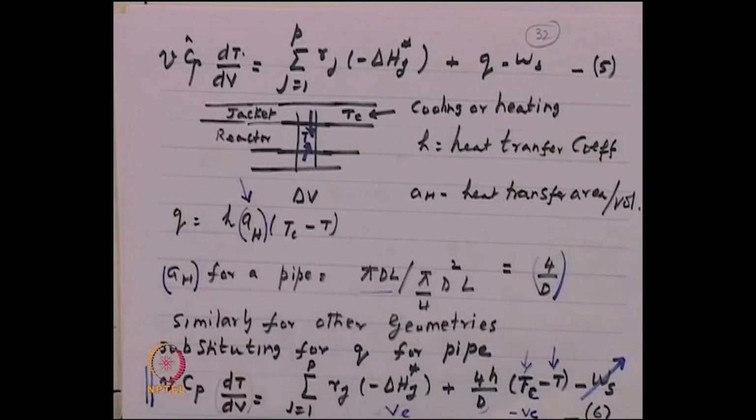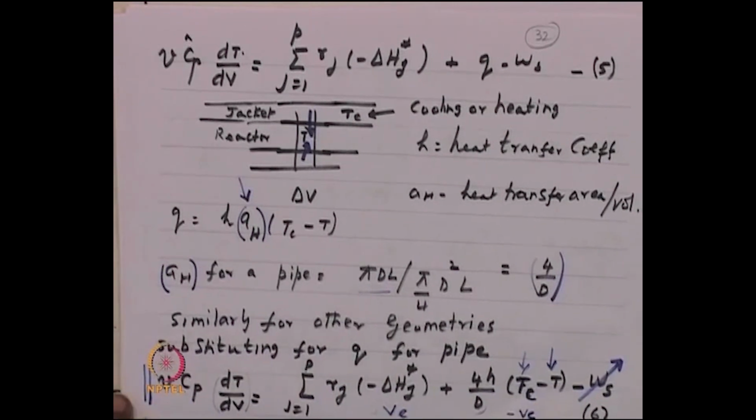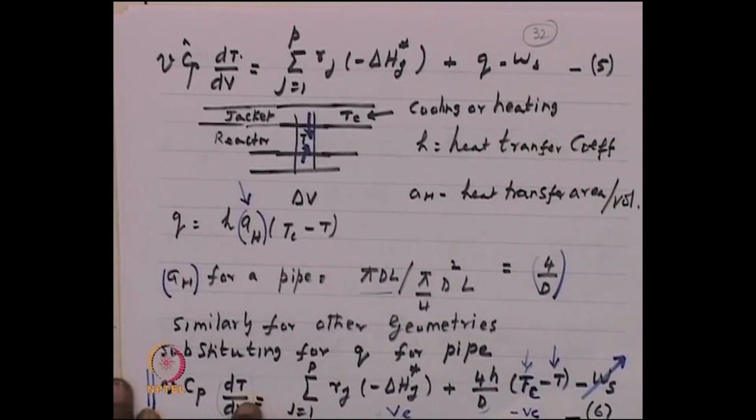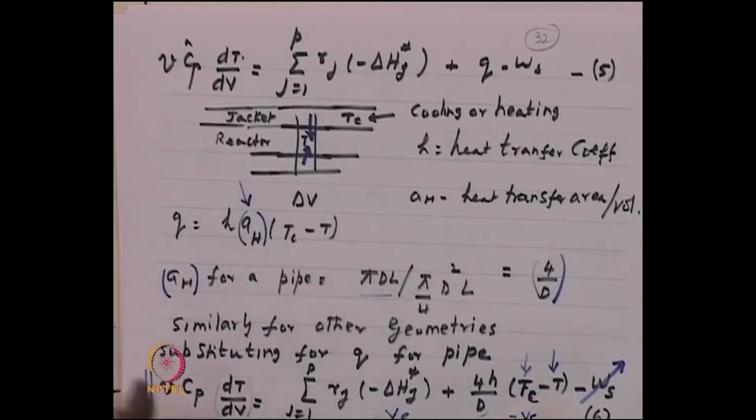When you use a large pipe, it is not able to dissipate heat very fast, and therefore, the hotspot temperature goes up. You understand? So, when you solve this equation, these are the points that are of great importance to us. What is the choice of D, so that this temperature is what you would like to see? Or in other words, when you do your numerical calculation, what will you do? You will choose different pipe sizes and generate this hotspot profile and see which profile is acceptable to you. And you will choose that profile, or that pipe size, which is acceptable to you. Okay.